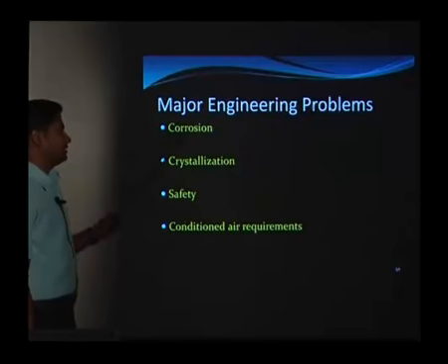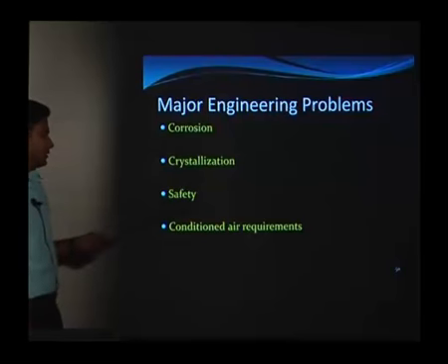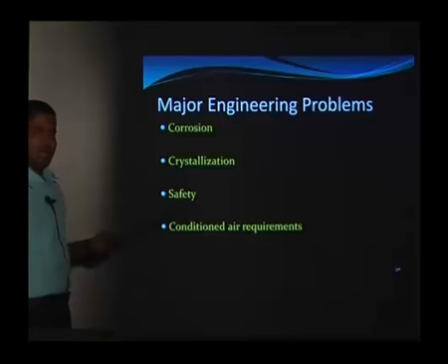Then the major problem in this one is the corrosion problem by the NH4NO3, then the crystallization in the crystallization unit, then safety because it is highly explosive, and conditioned air requirements. It should not have any contaminant, and the conditioned air should be such that it is free from contaminant and it can dry efficiently.